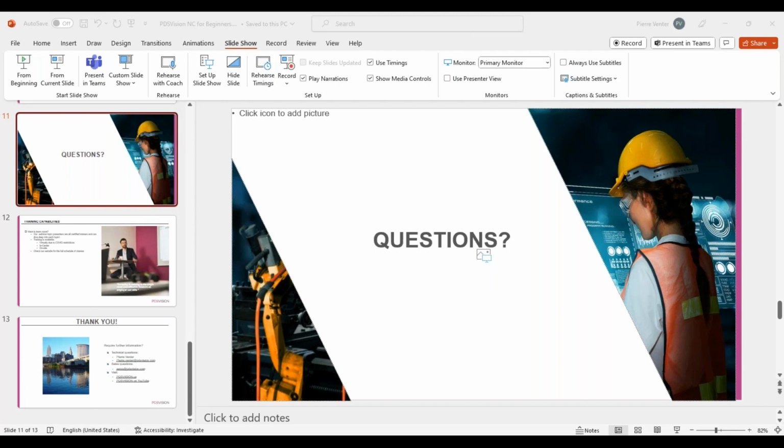So model-based dimensions, or model-based definitions: no, they are not part of the Creo toolpath generation, so it's not going to look at those. Once again, you can get tricky and create parameters and things like that and then reuse that, but it's not really going to make a big difference on the toolpaths that you generate.